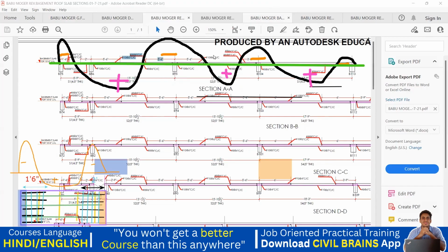So if I can bring it down, now you see the trend. We had a negative bending moment, so you're providing a top left extra, top right extra. You had a negative, you're providing a top extra. Negative, you have an extra bar. Sagging bending moment, bottom steel. Now one question may come in your mind. Wherever there is a negative, you told that top extra steel will come. Then why is that? I'll clear everything now.